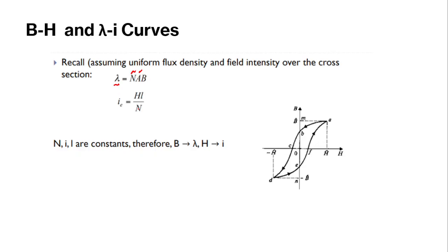What this tells you is how the current changes with respect to the flux linkage. If you keep increasing the current, the magnetic field strength will increase. But it will have a maximum point. That maximum point occurs when all the domains point in the same direction. That is the maximum flux density you could get in any material, so the material will saturate. You could keep increasing the current past that point, and it won't give you any further increase in B.